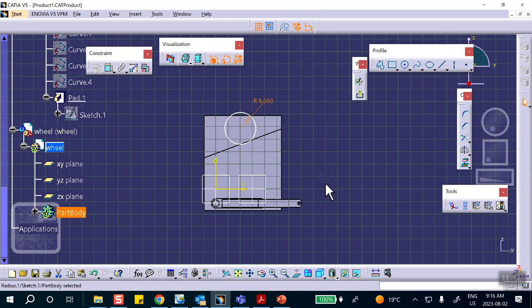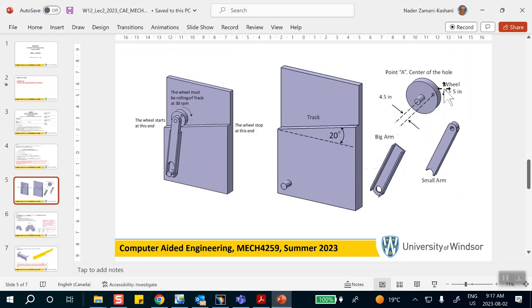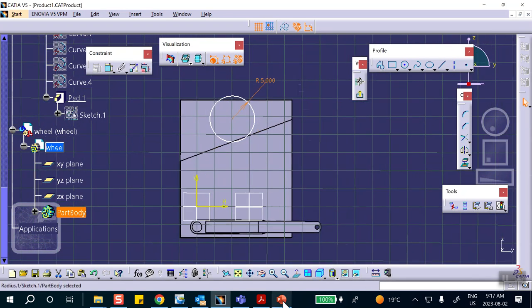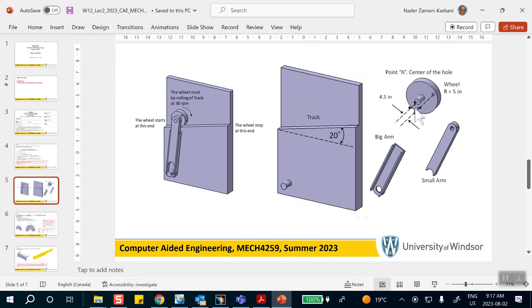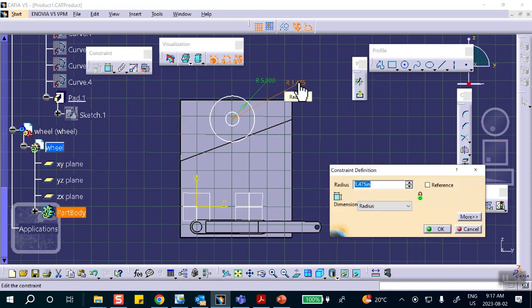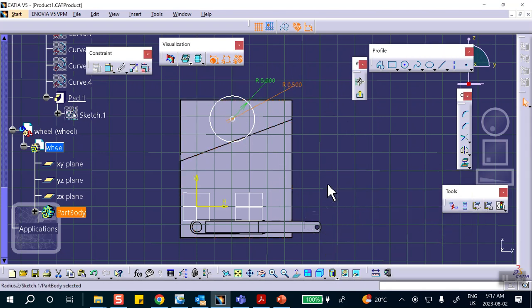All right, let me see for a second. Radius of 5, okay, fine. So let's see, how is that? There's a hole, there's a spoke here, and there's a little hole there. This hole is supposed to go into that spoke. So why don't I make that radius 0.5, so that these are almost the same size.